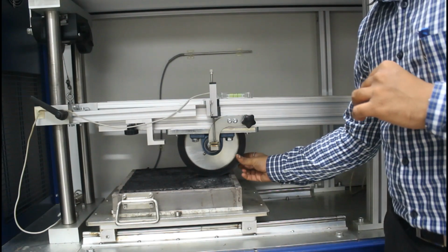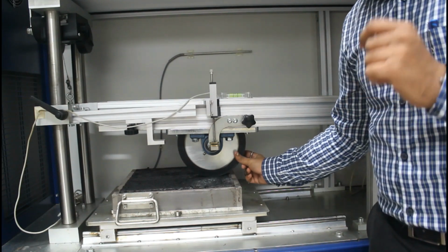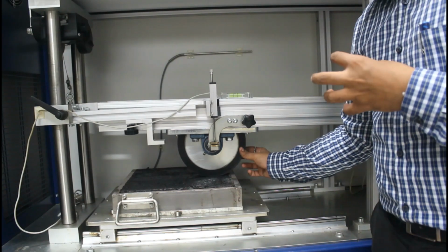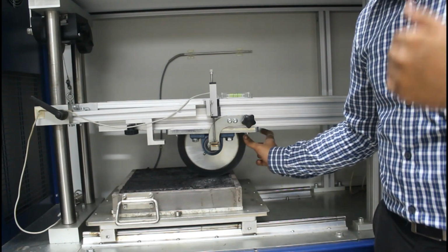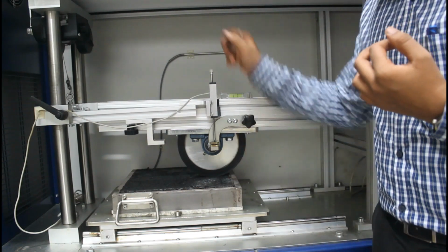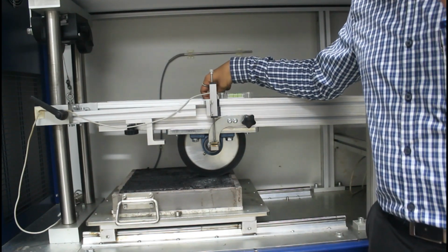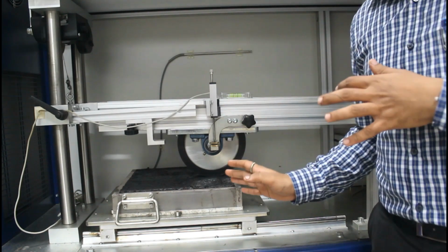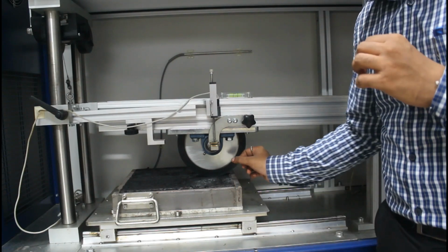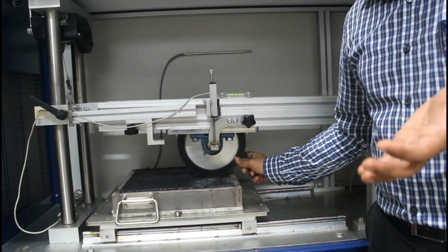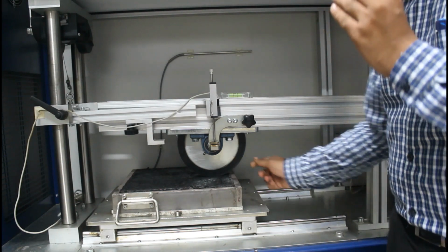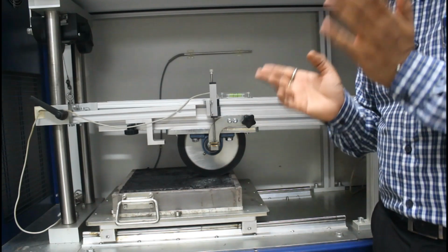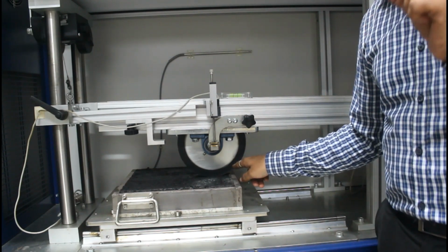If you see this particular wheel, the hardness of the rubber also matters. It matters what kind of rubber you're using. If it's a steel wheel, the results will be different. If you're using a studded wheel, the results will be different. If you're using a rubber of a given hardness, the results will be different. Normally, whenever you do any rut testing or the wheel tracker test, you need to specify the hardness of the rubber, right? It can be 80 or 90 or 70. So you need to specify the rubber hardness whenever you use the wheel tracking device, because the results depend on the rubber hardness also.